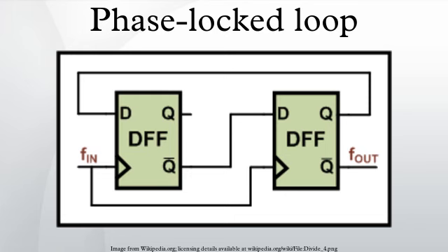Variations: there are several variations of PLLs. Some terms that are used are analog phase-lock loop, also referred to as a linear phase-lock loop, digital phase-lock loop, all-digital phase-lock loop, and software phase-lock loop. Analog or linear PLL: phase detector is an analog multiplier. Loop filter is active or passive. Uses a voltage-controlled oscillator. Digital PLL: an analog PLL with a digital phase detector. May have a digital divider in the loop. All-digital PLL: phase detector, filter and oscillator are digital. Uses a numerically controlled oscillator.